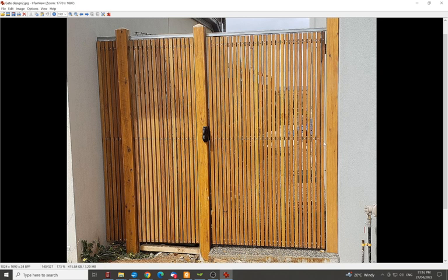In this case I wanted thicker rails. You can't see the back, but it's all powder coated rails. This one will be powder coated later. That was a bit of an afterthought, because this is a Hebel wall, and the post was coming off the wall. It wouldn't fasten to the wall properly, so we had to put a bar across here and check it in to strengthen this so it would stop leaning in. It's a bit annoying, because that's the problem with some of these Hebel houses.